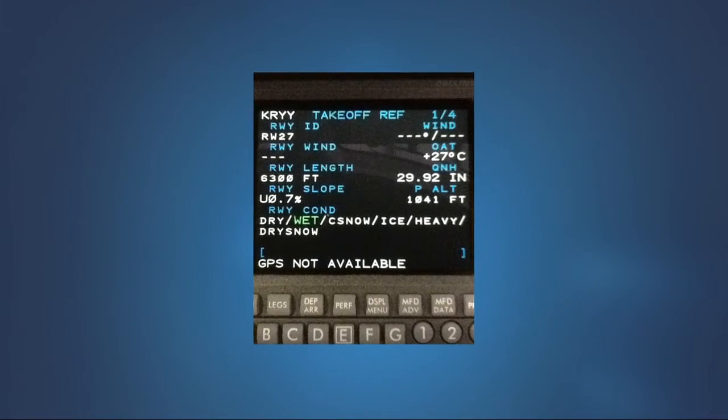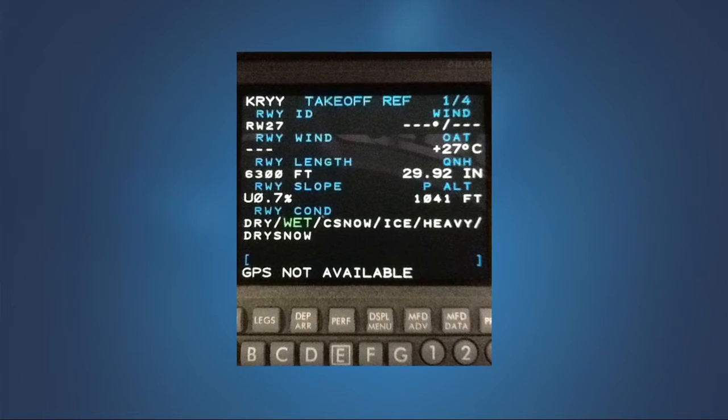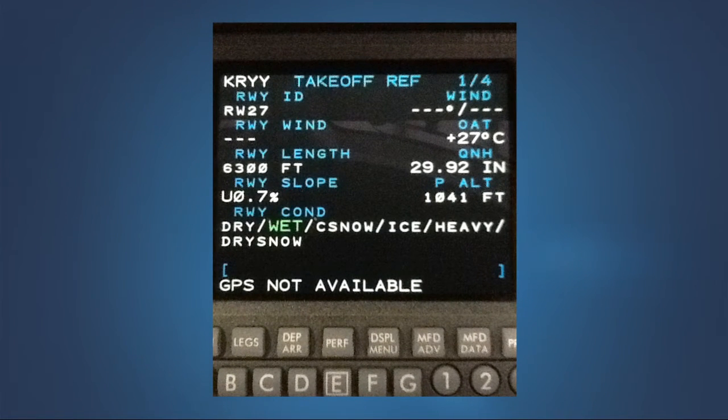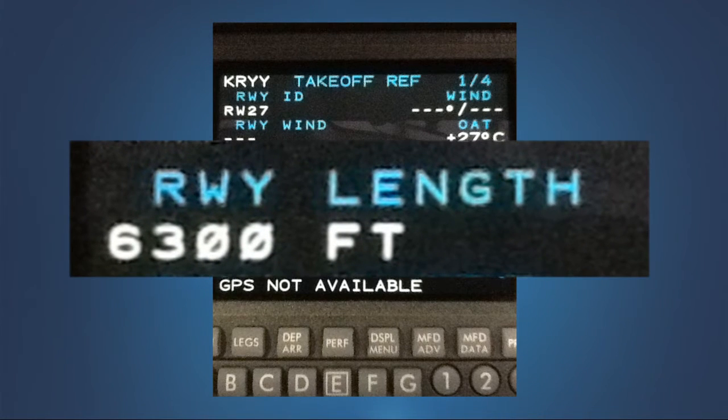Flight management systems for many business aircraft incorporate performance calculation functions. These functions can compute the takeoff and landing distances required for conditions and have the capability of calculating the maximum allowable takeoff or landing weight for a particular runway. However, these calculations are based on the runway information stored in the database.